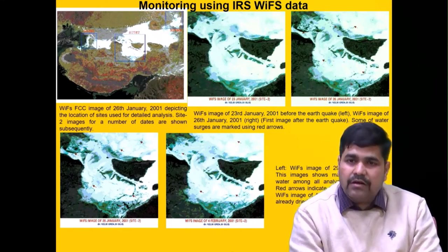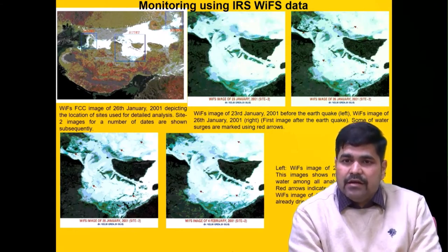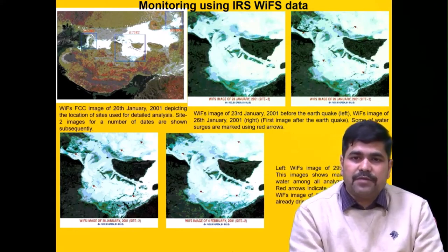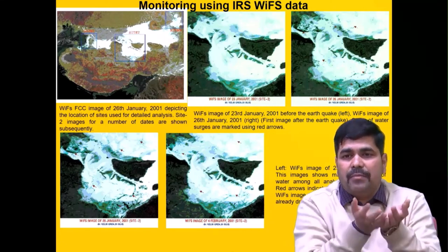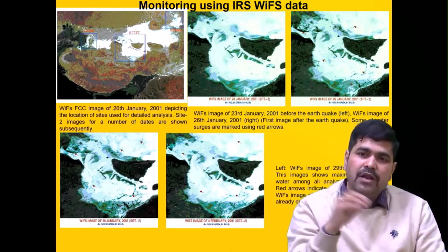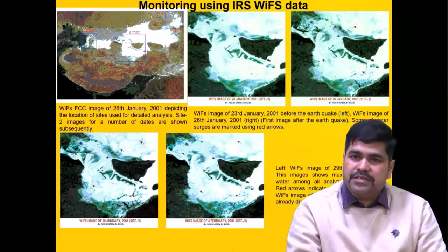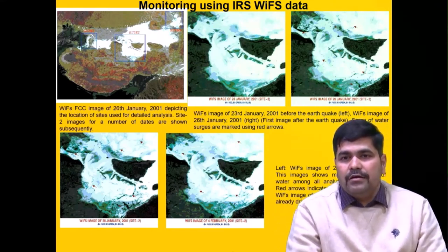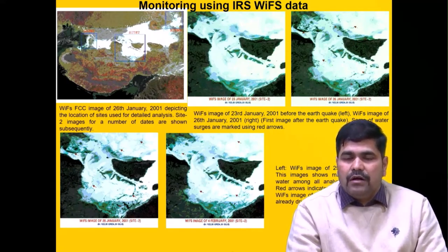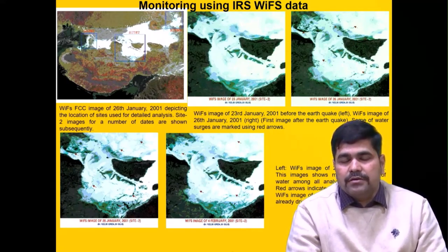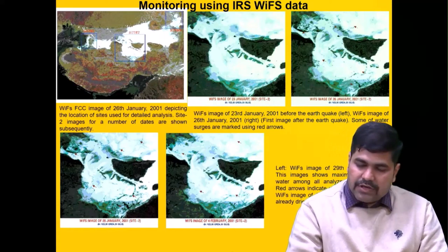We can keep our maps ready where there is a chance of shallow subsurface water coming up during seismicity, and the buildings falling in that zone should be evacuated, or at least they should be earmarked, and mitigation and rehabilitation should be positioned in a nearby location, so that whenever it happens, we at least can position our measures. We can be prepared with remedial measures in the nearby location.